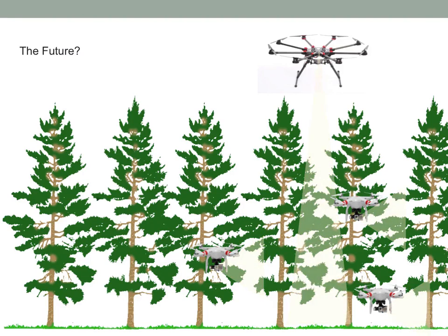There's also technology being developed. There's a few papers out on collision avoidance. They'll put small sonic sensors and small LiDAR sensors and small image sensors on these platforms so that you can fly it in one direction, and if there is an obstacle, it'll sense that obstacle, recalculate its trajectory to go around it or above it or below it, and then continue back on the track that it was at. So potentially, I can see where you would be commanding a swarm of drones and telling them to go cruise for you and fly into the canopy. They'll calculate your height, your diameter. One can fly above, take photographs, calculate your species, and then you process all that data back in house and end up with a 100% inventory of what exists.